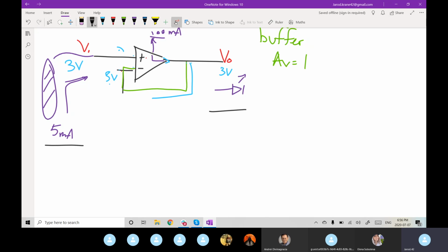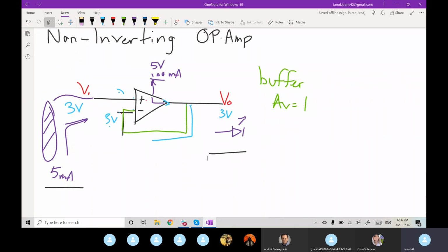Not too sure on the power loss through the op-amp compared to the MOSFET. I know you can get MOSFETs with very low RDS ons, so potentially the power loss wouldn't be an issue compared to, but I can't say for certain.